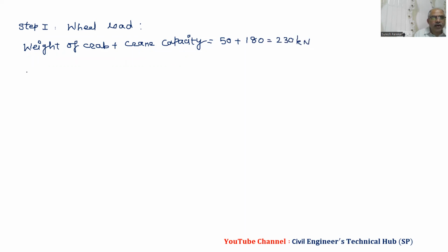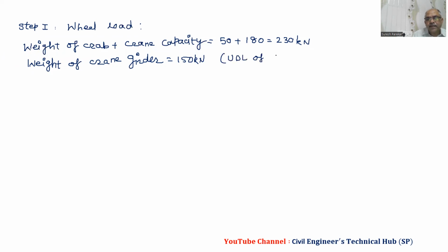Then we have weight of crane girder, 150 kilonewton. This will act as UDL on the crane girder.